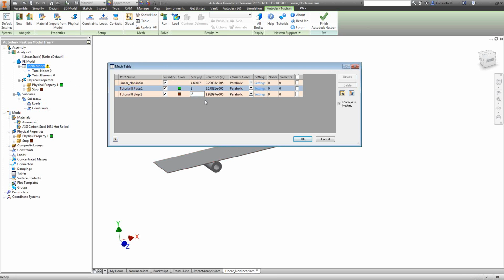In Inventor Pro, your mesh control is very limited. There are definitely times where I'd like to say I want this mesh size. And obviously with small features, it's going to increase the mesh density as you get the small features. But in general, I want this exact mesh size. You can't really do that in Inventor Pro. You're sort of limited to a percentage of the bounding box of the material.